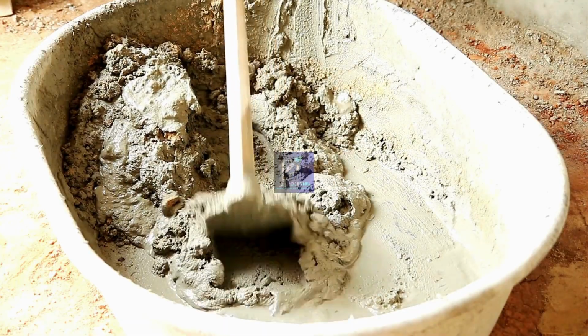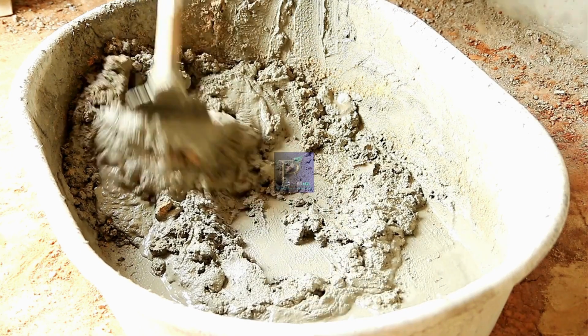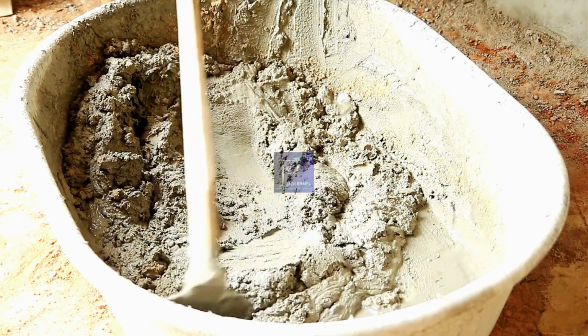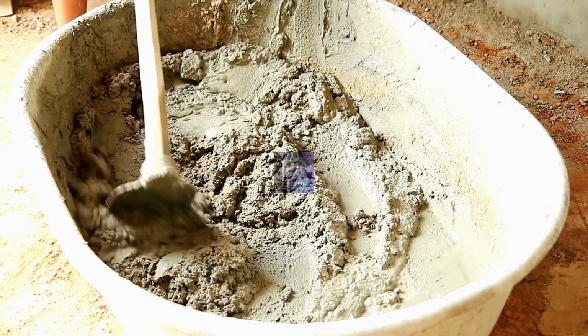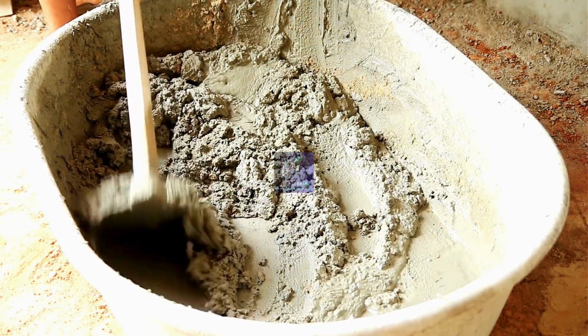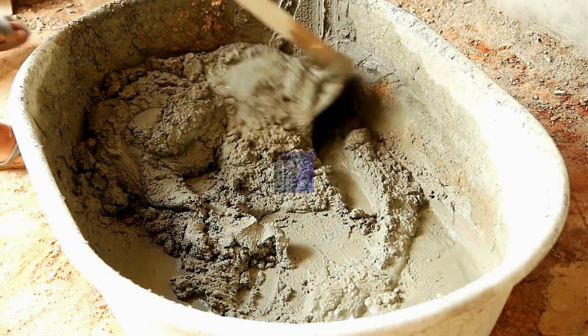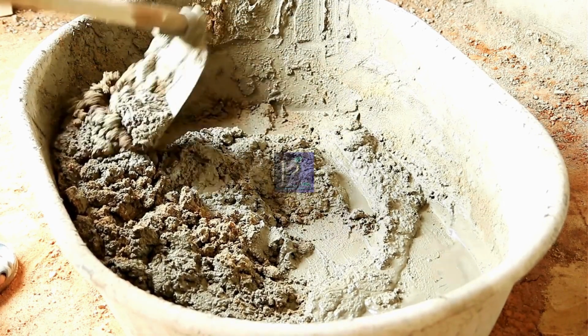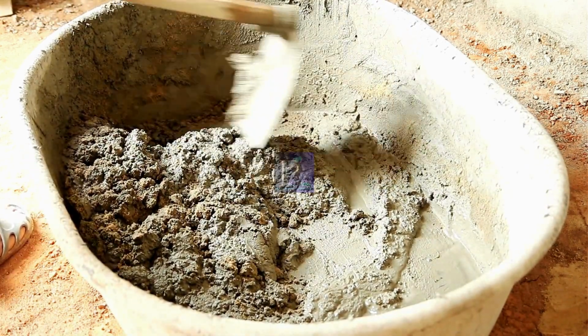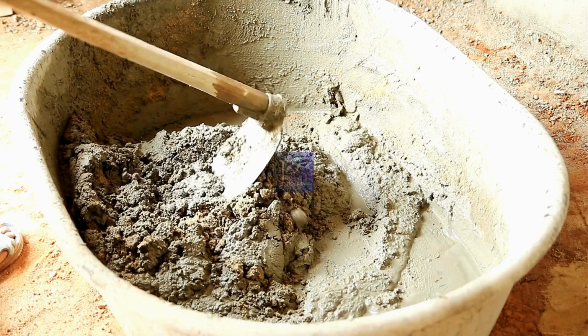Setting time of cement, average residue percentage for fineness, soundness of cement measured after boiling for a specific duration along with the mold, and importantly, the compressive strength of the cement mortar cubes. All these materials undergo various tests to provide the input necessary to finalize the design mix.